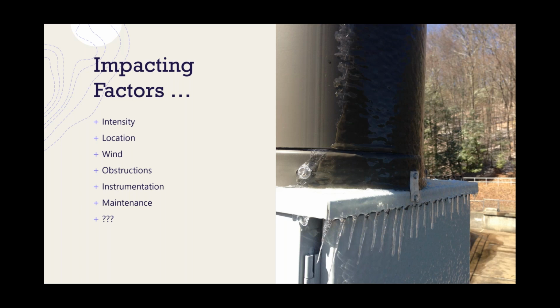I remember seeing many years ago a study that said in the typical standpipe, what we all grew up with in the ALERT world, for a 10-mile-an-hour crosswind blowing across the gauge, you may lose 10% catch. So, whatever you can do to reduce the wind impacts on your rain catch would be worthwhile. Obstructions goes to just simply that. You don't want trees growing over the top of your rain gauge.